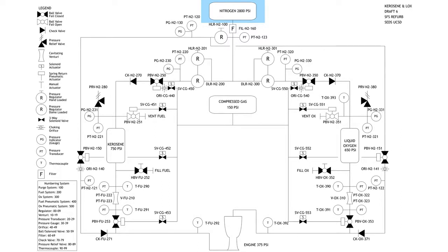And we don't have to worry about solubility issues with N2 and O2, because I mean, N2O is an actual molecule of nitrous oxide. It's laughing gas, but that reaction won't occur inside of our system for a while, so we don't have to worry about it. Just don't let nitrogen sit on top of your oxygen for 4 hours, and you're fine. What happens is we pressurize our tanks and we fire within a minute.